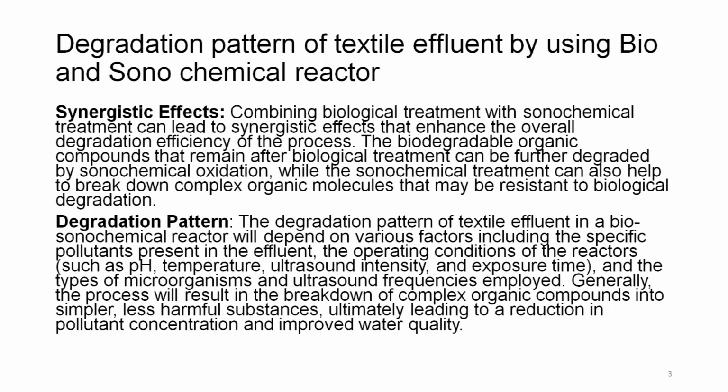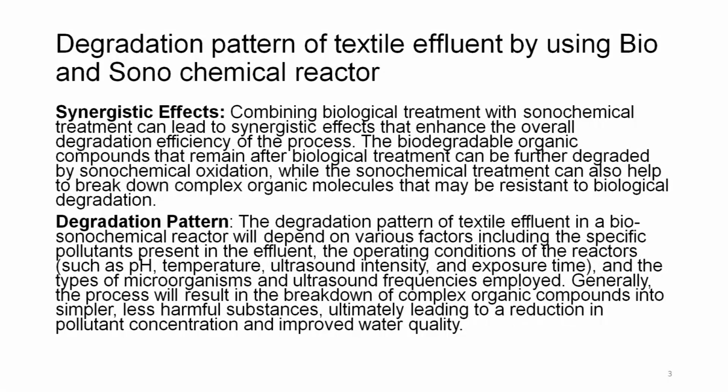The organic compounds that remain after biological treatment can be further degraded by sonochemical oxidation, while the sonochemical treatment can also help to break down complex organic molecules that may be resistant to biological degradation. So, what it means is that whatever could not be achieved by biological treatment could be attained by sonochemical reactors. Degradation pattern. The degradation pattern of textile effluent in a